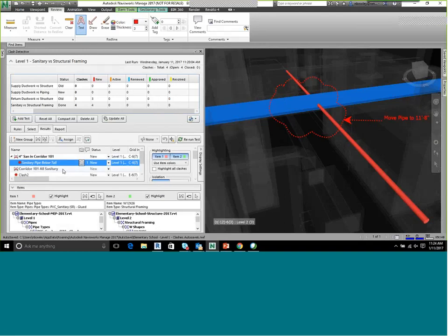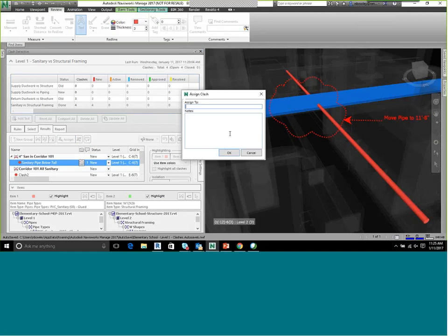When you add the comments, do it while you're in the clash report wizard. The reason for that is when I export all these clashes to HTML, which we'll get to in a few minutes, I want to see that comment in the HTML file. One mistake a lot of people make is they'll first save all their views as saved viewpoints, which I'll do in a minute, and then they'll make their comments. But the problem with that is when you rerun your report and then you export those saved viewpoints again, you've got to make all those same comments again if that clash still exists. So it's kind of frustrating. I don't recommend doing that. On top of making comments, you know, a digital comment or a comment that's visual, you can also assign it to a user or assign it to a person.